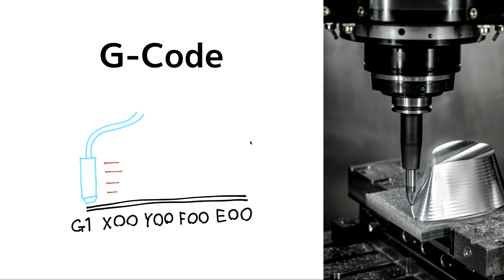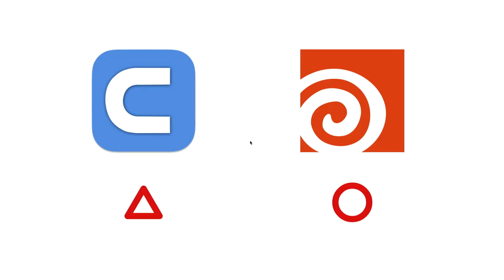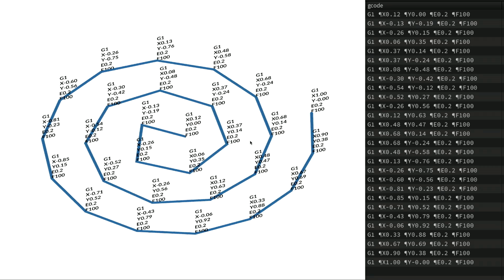For example, in 3D printing, G-code specifies nozzle positions, as well as speed and material discharge volume. Now, by generating G-code directly in Houdini, you can have more flexibility and control over the fabrication process instead of relying on a slicer, like Cura, that comes with a 3D printer, which will generate your G-code automatically using your STL model. But if you could generate your own G-code, then you could have more control over the printing machines.